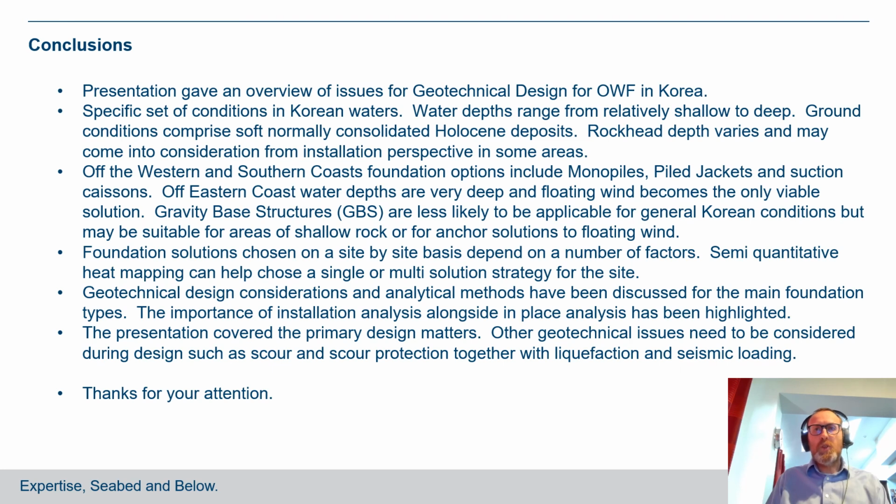Okay, just to conclude and wrap up, this presentation has given an overview of the issues for geotechnical design for offshore wind farms in Korea. There's a specific set of conditions for Korea. Water depths can range from relatively shallow to quite deep, and the ground conditions are quite challenging, comprising soft, normally consolidated clays and deposits. Although in some areas rock can be quite shallow and could cause problems from an installation perspective.